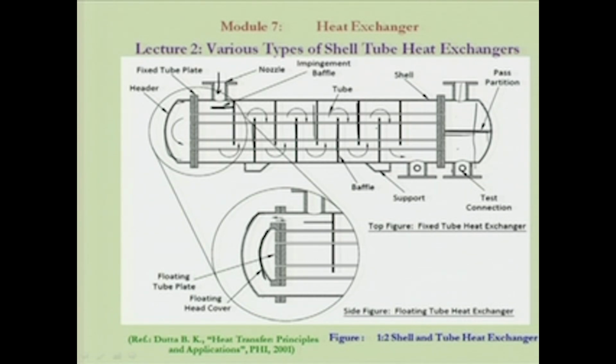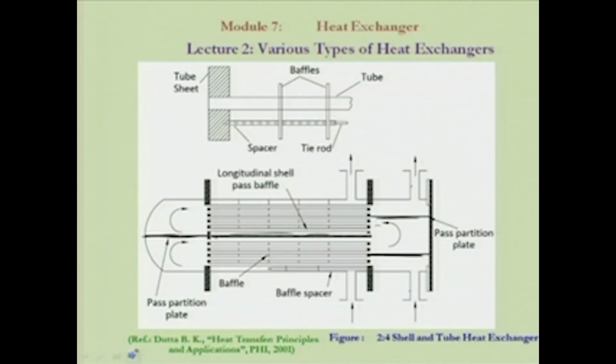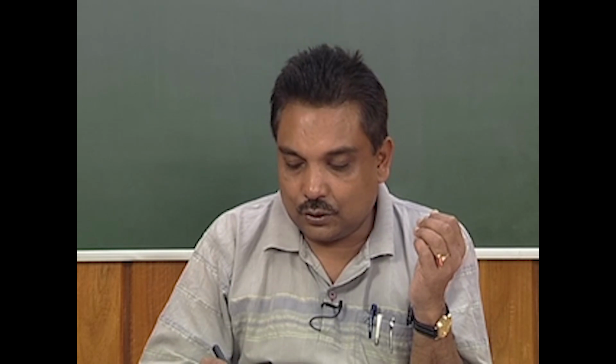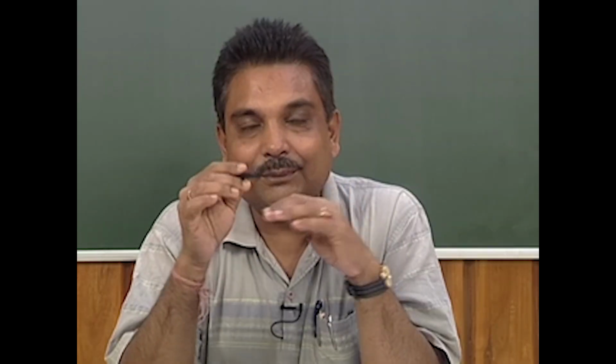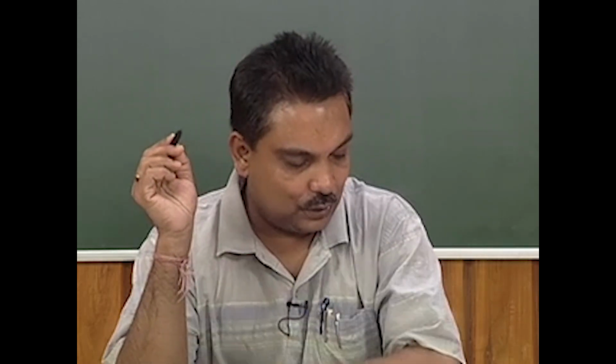It is a circular kind of plate, simply like a tube seat, and through that there will be some holes, and its diameter should not be equal to the diameter of the shell. Otherwise, there would be no passage for the shell side fluid. So, there will be some segmental cut. The baffles will be cut into different segments. Therefore, we call them segmental baffles.